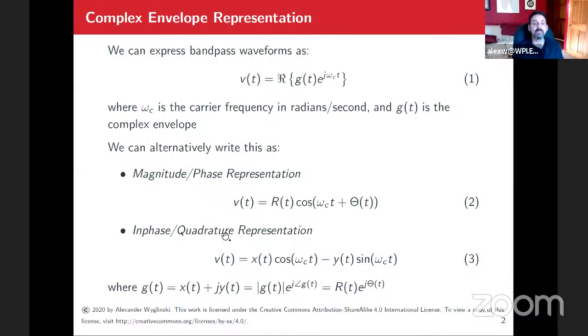Okay, and then the IQ. Okay, so that's the thing. That's magnitude phase, and then you're going to hear this a lot. It's going to be called IQ. And the IQ representation in phase and quadrature is that Cartesian representation I was telling you about, and that's what table 4.1 also provides.